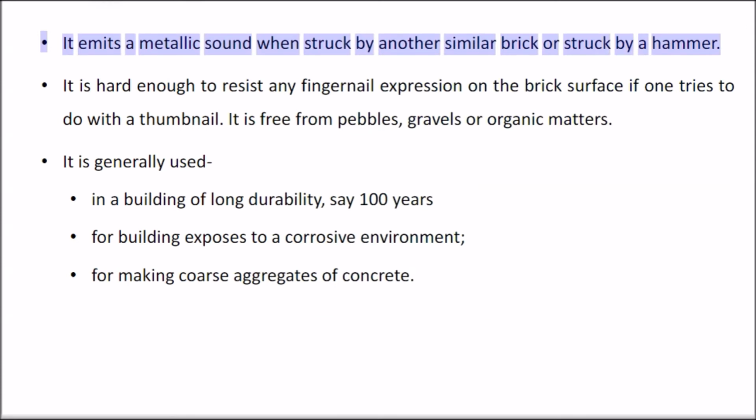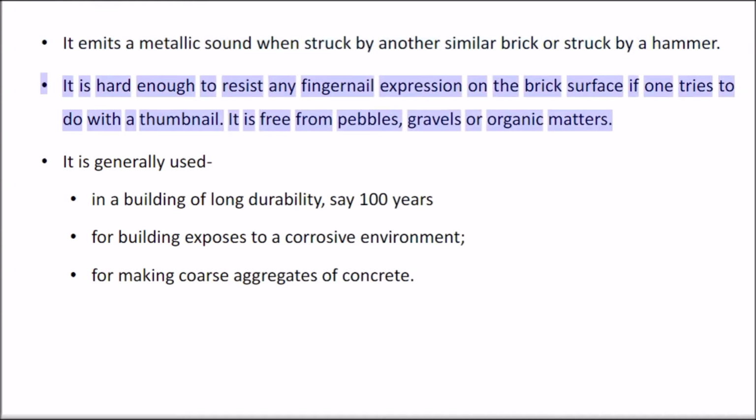It emits a metallic sound when struck by another similar brick or struck by a hammer. It is hard enough to resist any fingernail impression on the brick surface if one tries to do so with a thumbnail. It is free from pebbles, gravels or organic matter.